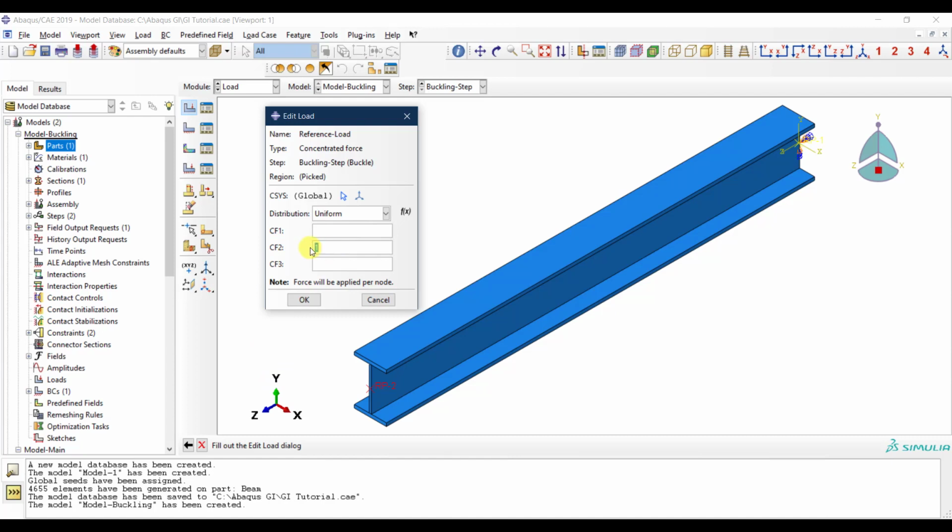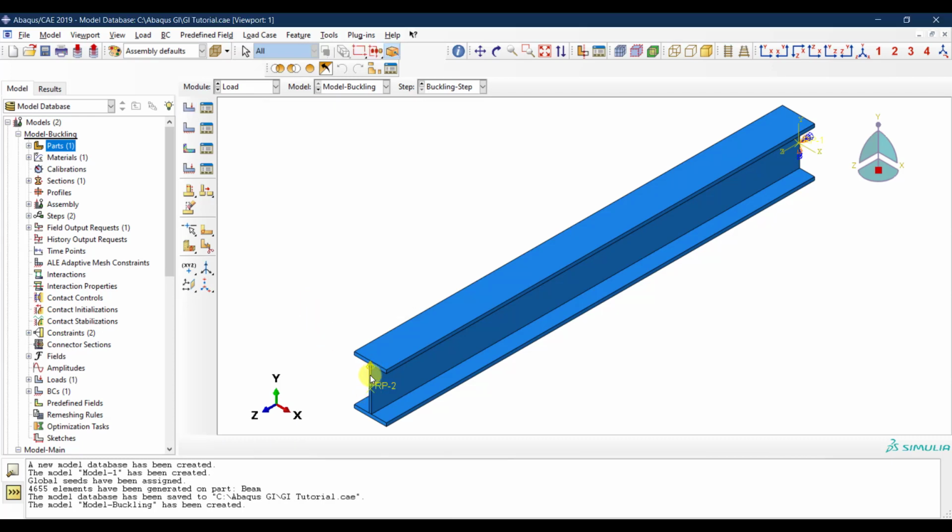So essentially at the end, once we get the buckling modes, you are going to get the eigenvalues. And the eigenvalues represent the buckling load corresponding to this buckling mode. All right. So if we take these eigenvalues that will appear after we do the analysis, if you multiply those by the reference value, then you get the value in Newton, in our case. So that's why I put here unity, like you don't need to put something different. So I'm going to say okay. So now I have my reference load. Again, it doesn't matter the direction. And that's it. If I wanted, I could have put a reference load like a compression on the column so that I will get some modes that are representative of the compression. So that's it.